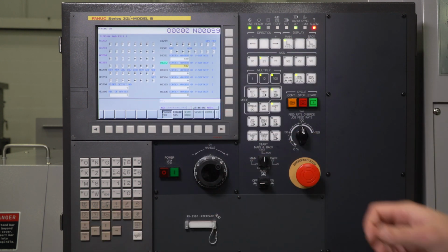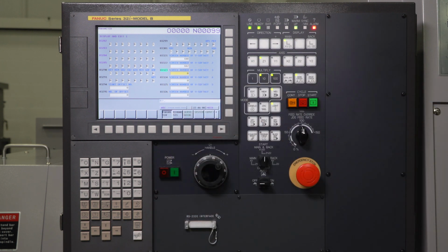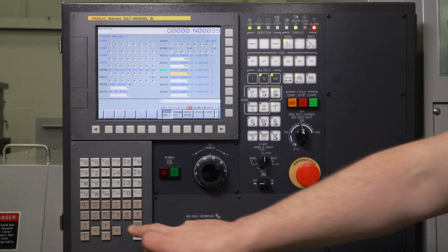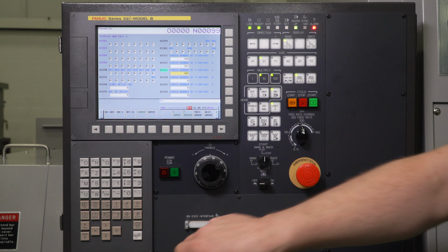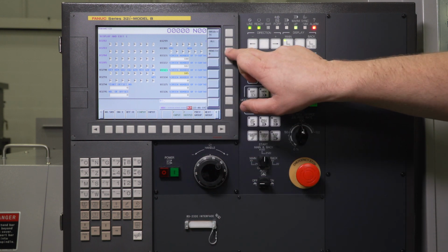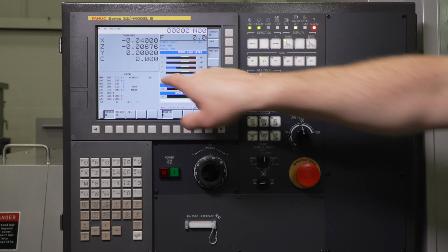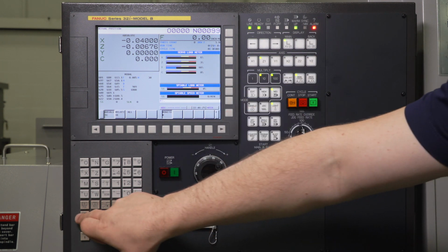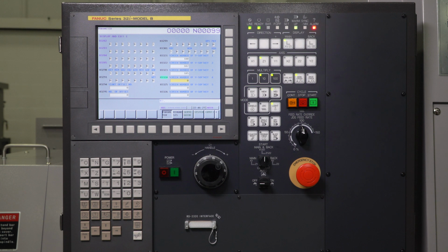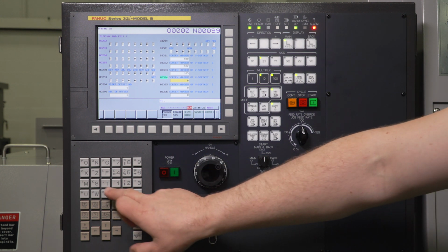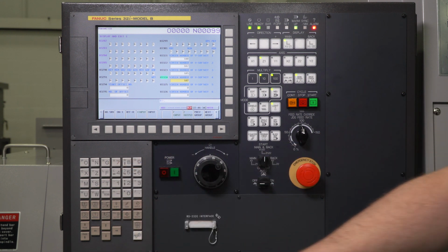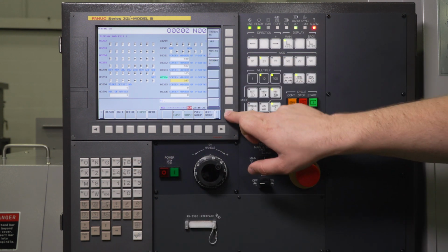Back to system. We're going to go down to 3323. We want this one to say monitor. This is going to be our load monitor for our axes. So we'll make this a 105, input, and now I have monitor. I press monitor, and it's going to show me my servo load monitor for the X, Z, Y, and Z axes. Back to system. We're going to go to program screen, which is going to be 107. 107 is going to give me my program screen.